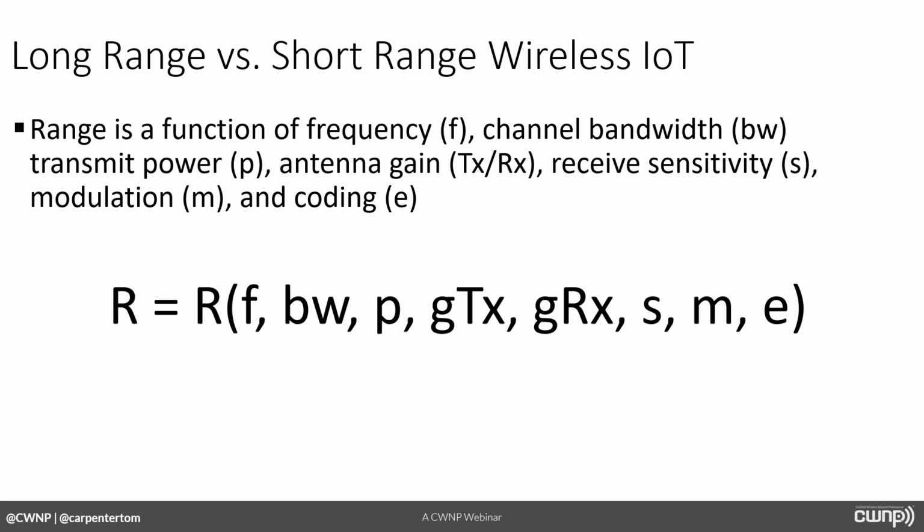Now, for health reasons, as well as interference and cooperative reasons, there are limits on the output power based on regulations around the world in different regulatory domains. So we can't just keep turning up the power to get a longer and longer link. We might like to, but we can't do that for, first of all, regulatory reasons, because the regulatory bounds are well below any kind of health risks. So there's the regulatory reason, but then eventually you would get to a health concern if you went with transmit power too high.